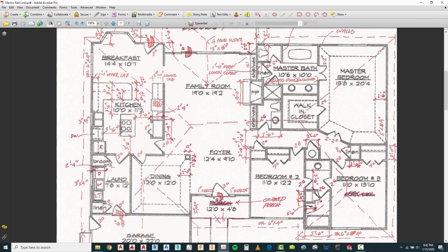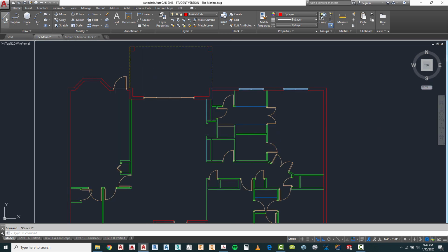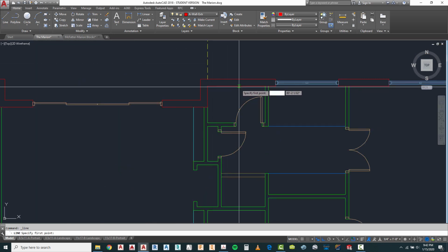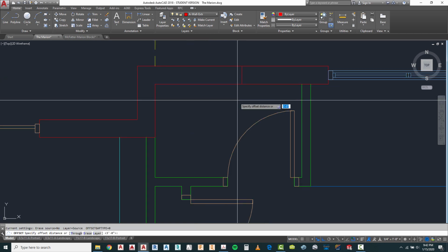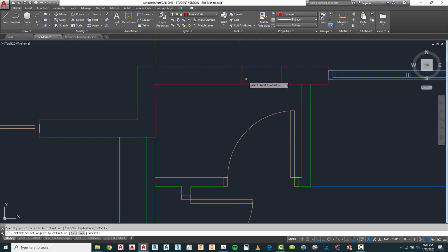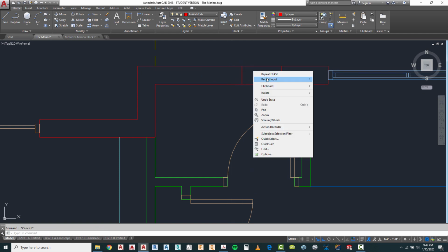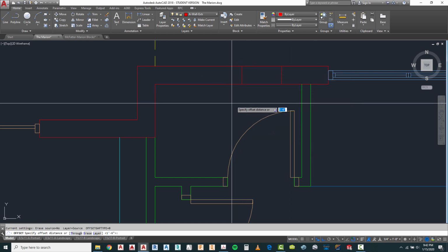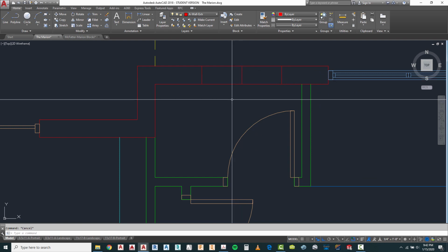We're going to put a 3-foot window in here and a 3-foot window at the edge here. Let's go back to our drawing. This time, let's go ahead and draw in here. This one doesn't necessarily need to be in the middle, so I'm going to offset 1'6" in this direction and 1'6" in this direction. Let's try that again. There's an input offset. It's defaulted to 1'6". Go ahead and click that one.